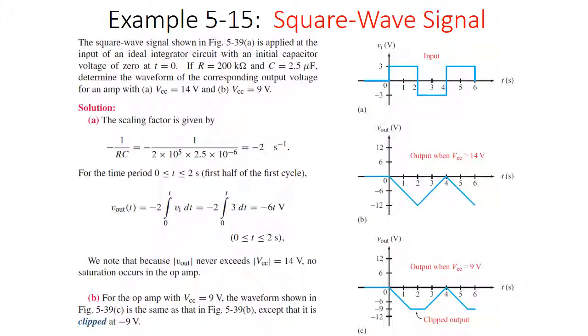If our op-amp was 6 volts, plus or minus 6, like the MCP6004 op-amps that we have from Microchip, you're going to clip that output even higher. So it's going to be up higher. At that minus 6 volts, you're going to go flat right over there. So it's going to be probably from time t equals 1 to t equals 3 that you're going to have your flat peak, and there's going to be no slant in there.